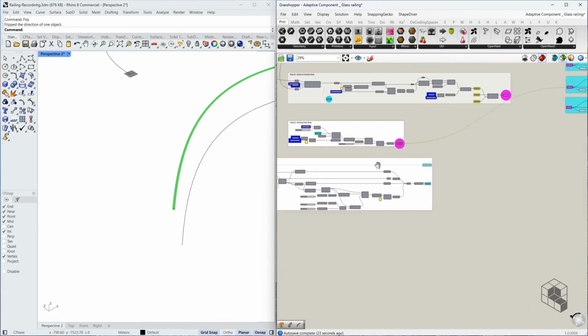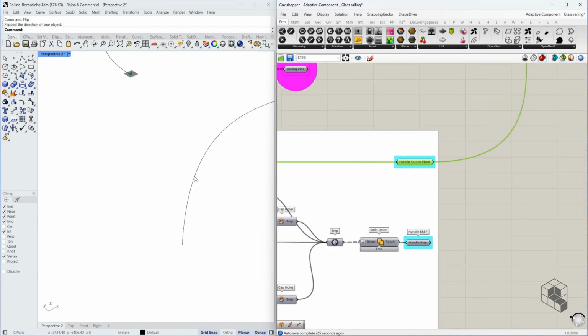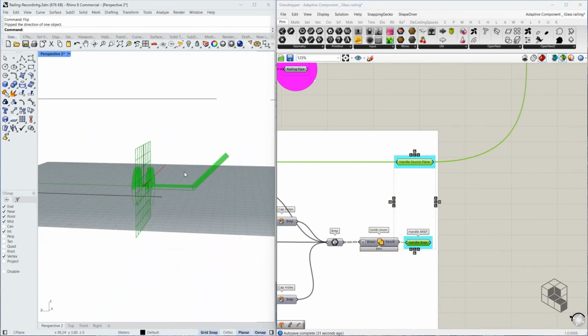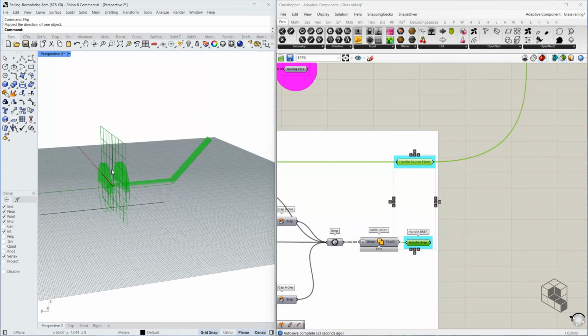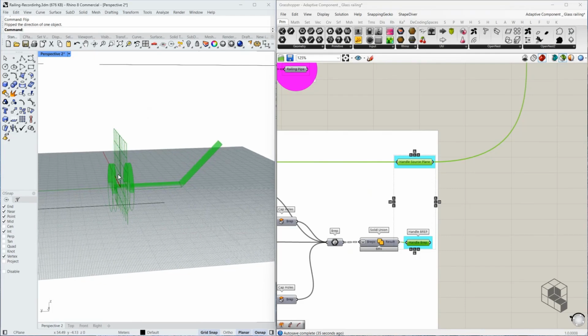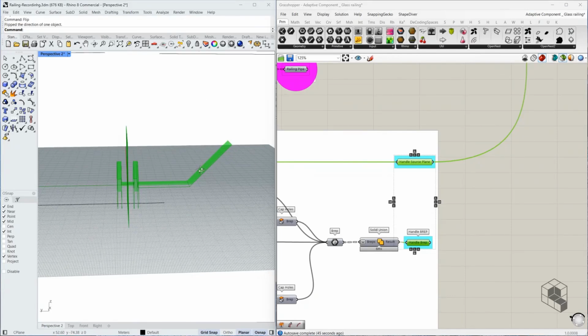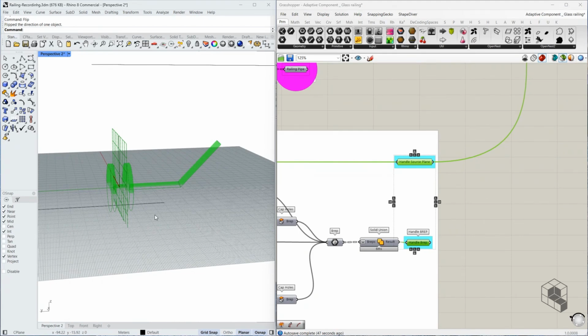The seventh step involves creation of individual handles. Now, here we have created this joinery detail where you have this knob system and you have this gap where the glass sits, and then you have this connecting pipe which goes and connects to the handrail.